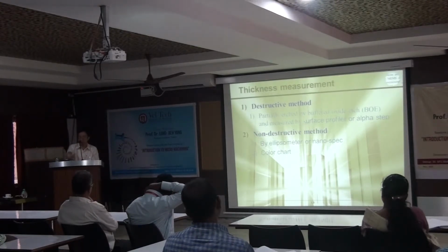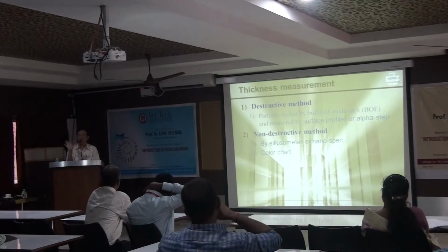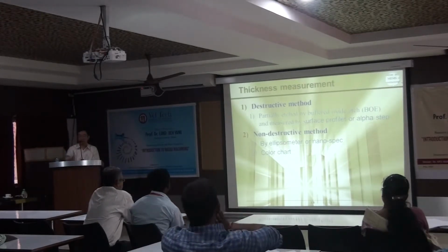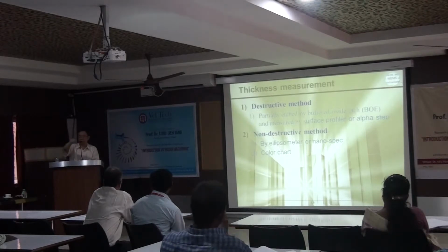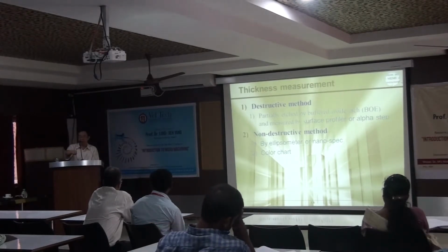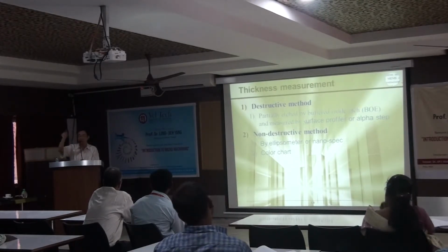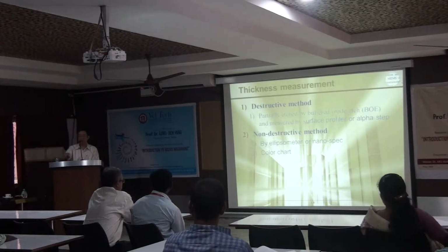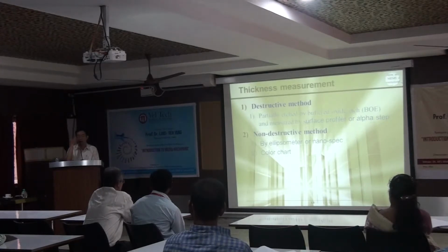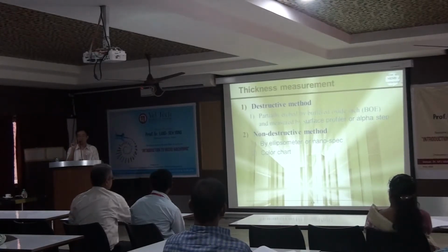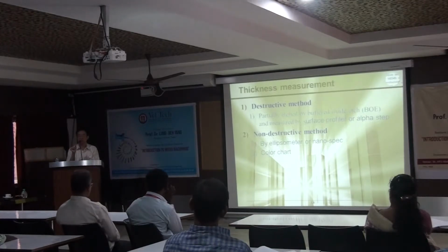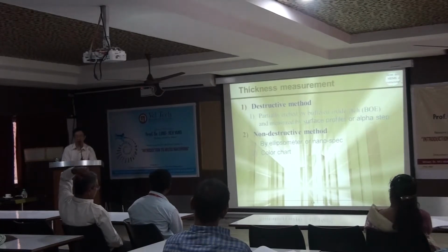Because oxide is transparent. It's naturally no color, transparent. But one ray touches the surface and reflects, while one ray penetrates the oxide and reflects back. So there is some lag between these two beams, and they give you an interference effect. So only some specific light you can see, only some frequencies can be visible. That is the reason why we have different colors.